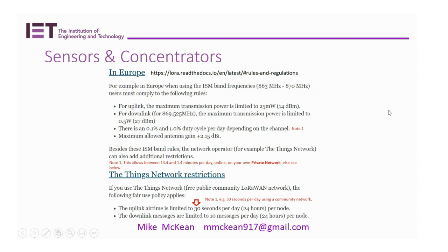So as you're moving around in this environment and hear people talking about LoRaWAN, just make them aware, ask them to do a Google search on availability of these environments, because people actually deploy, because LoRa can work 5 to 20 kilometers. If you're in a desert environment, it could work maybe 20 kilometers or further, and you say, well, there's no one around here, I'll just hog the bandwidth all day, 24 hours a day. But what if someone else opens up next to you with their environment and complains? Then you've got a problem.